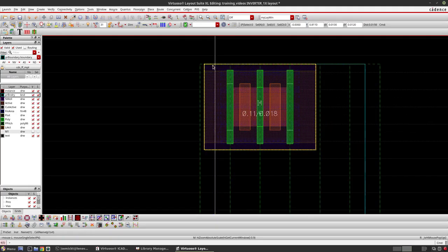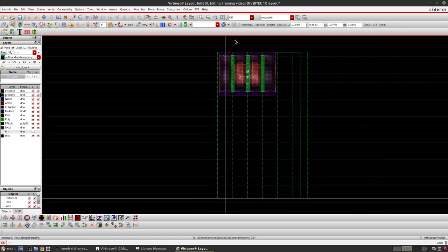Okay, so when there is an adjacent cell coming here, it will get overlapped, and the next poly edge that it will be coming here is here. So in that way, we are ensuring that the poly is always at 86. The poly pitch is maintained, and the next poly adjacent to it will be coming exactly here, right? So the poly pitch is maintained to be 86 nanometer.